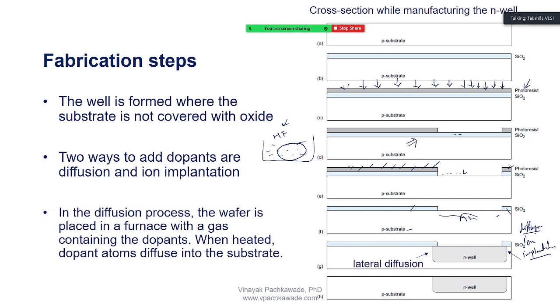We are not going to dig into details of that because those are fabrication issues and fabrication methods. So there are different chapters at different lanes where we can talk about that. But just remember, out of these two, nowadays in technology they mainly use ion implantation. So they select the dopant, what kind of dopants you want to fabricate N type semiconductor into the P type semiconductor. Now this is the P substrate, and we want to fabricate N well. So I will use the group 5 dopant, group V semiconductors. It could be arsenic, for example. Okay, arsenic. So I am going to have a lot of valence electrons in the outer shell.